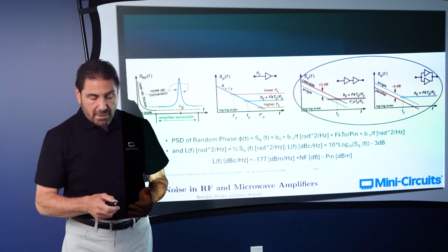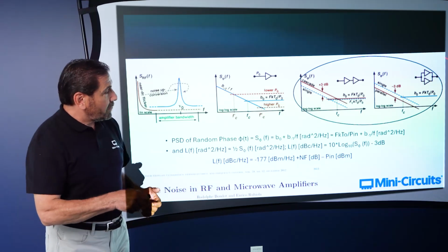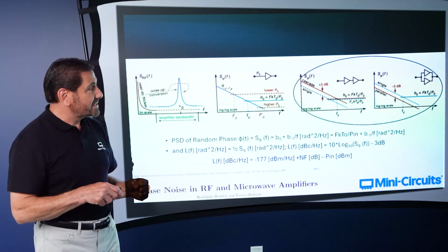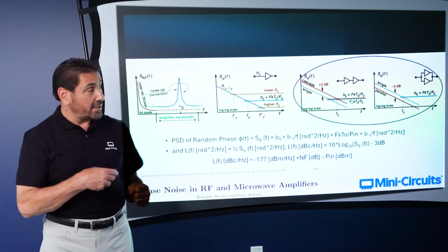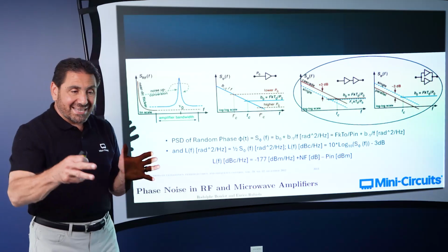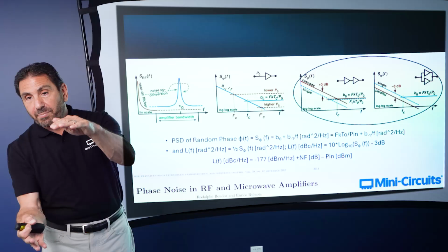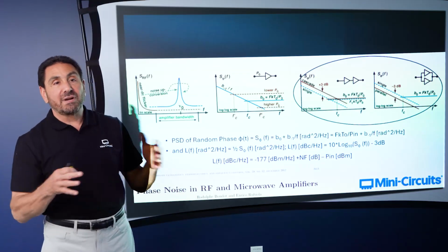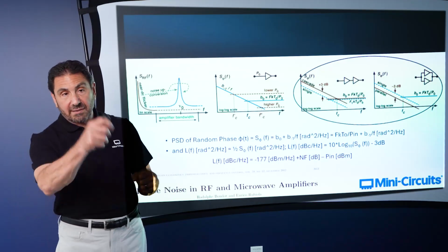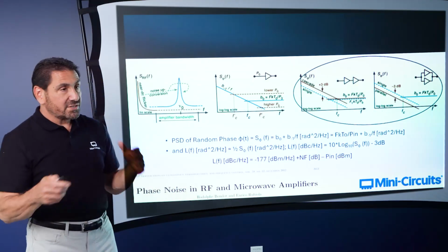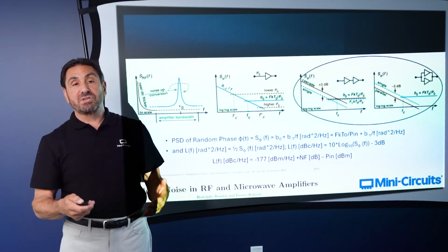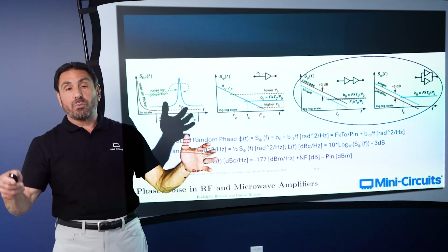Okay, so as with part 2, we're going to focus now on cascaded configurations, but we're going to do a single device feeding 4 in parallel. It's not on this chart, courtesy of Professor Rubiola, but it will be a cascade of a single device driving 4 in parallel. And again, we're going to look at different operating regions, different power levels input to the first stage and the combined 4 stage. We're going to see what differences there are, and can we find, again, a configuration that allows us to achieve optimum additive phase noise performance over a wide band.